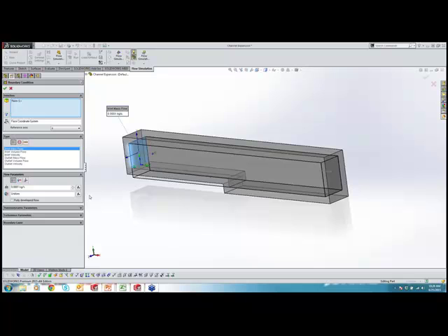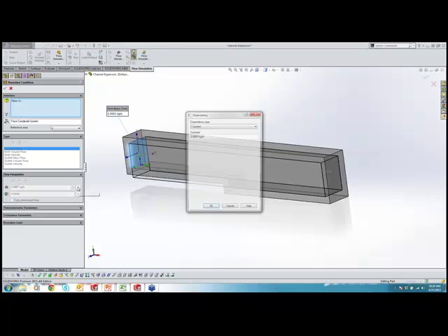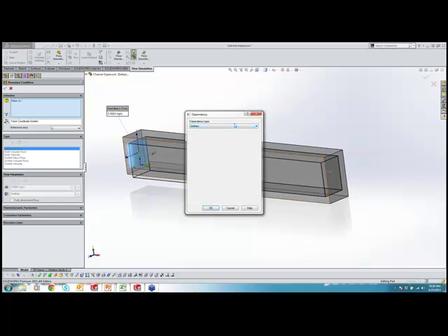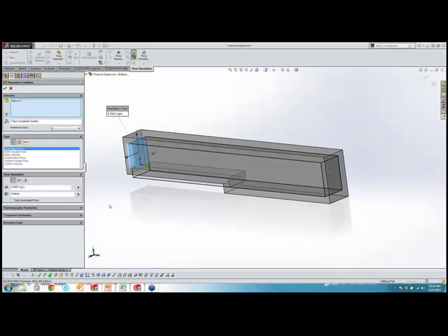Yeah, and if you can get any data for the mass flow rate, you have much more power in how you want to set up your flow fields. Because now, with your mass flow, if you know the flow profile inside the pipe before it's leaving, you can even specify that as a table, formulas, things. If you have radial flow ones, all of these have incredible amounts of flexibility in their dependencies.